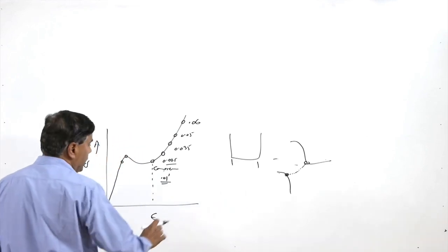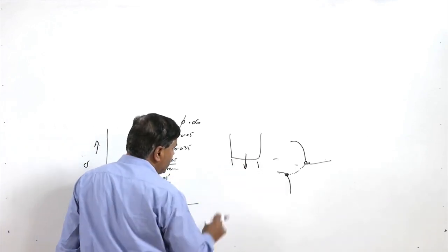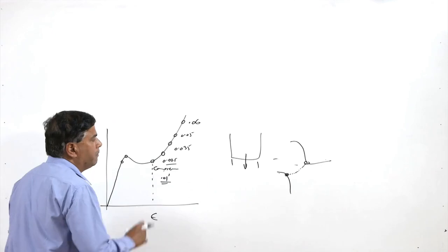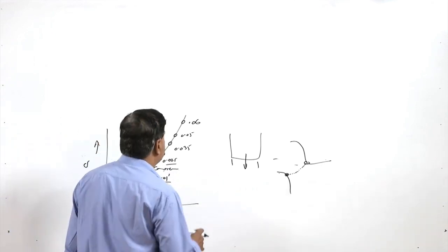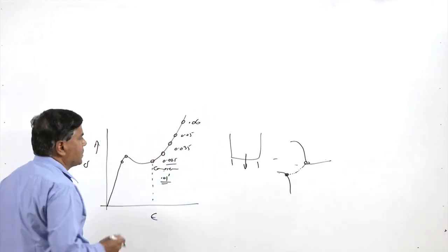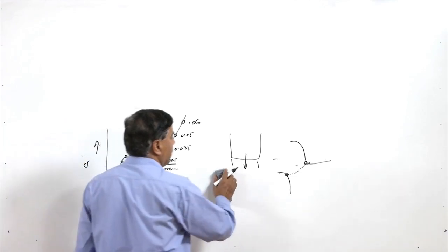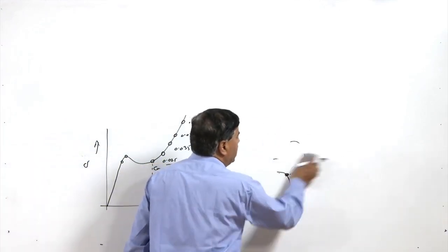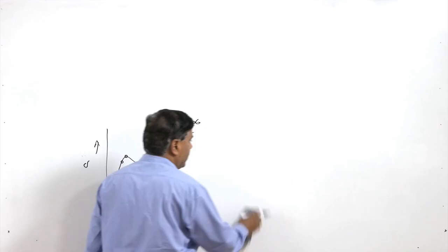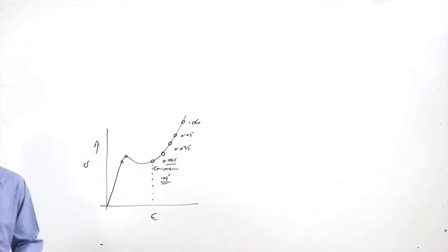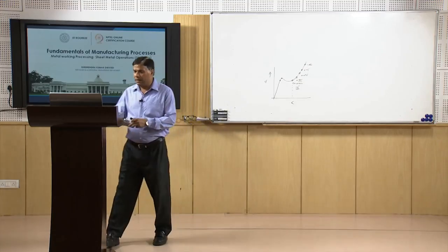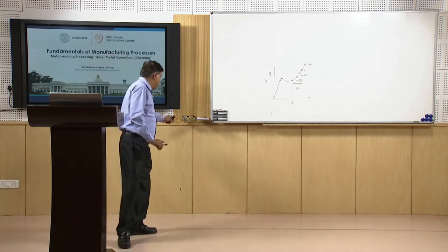at the center. So, with the increasing entry of the punch into the sheet metal, the compressive strain as well as the stresses will keep on increasing, and a stage will arrive when the cracks will nucleate on both the sides and their growth will start. So, that is what will be explained sequentially in the subsequent diagrams here.